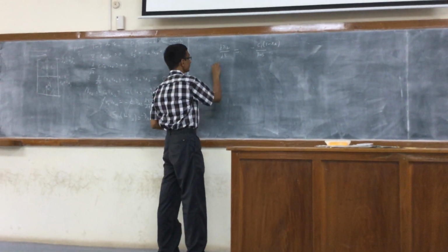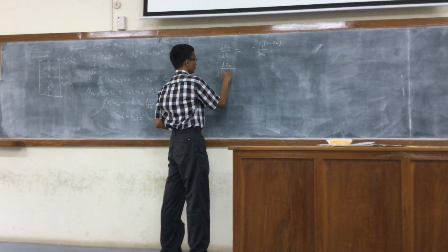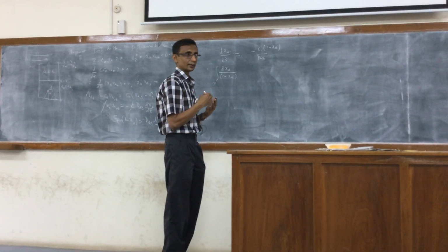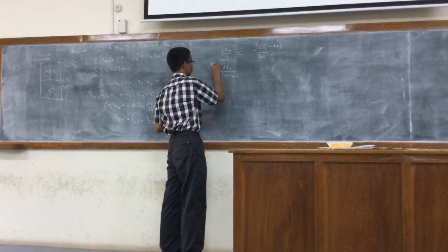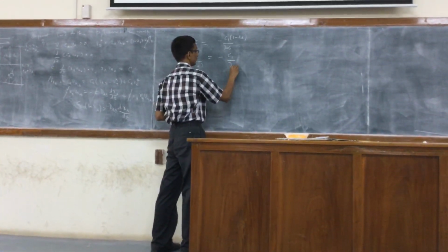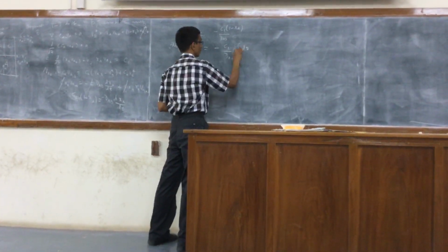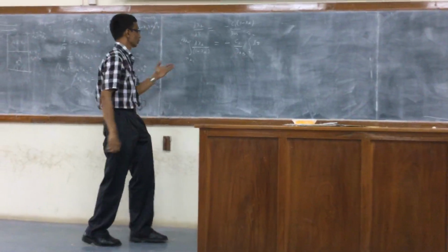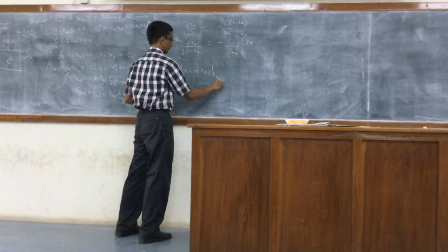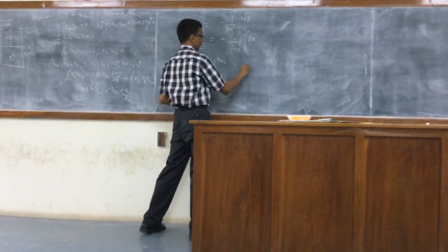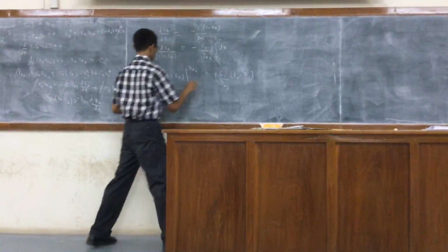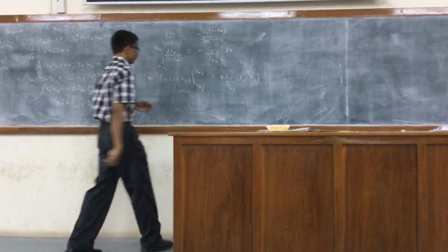So we now integrate this, it will be dXA by 1 minus XA. Suppose I integrate from, I can find C1 first by simply integrating this from XA1 to XA2, and then I have minus C1 by DAB dZ, Z1 to Z2. So this is minus logarithm of 1 minus XA between the limits, and this is minus C1 by DAB times Z2 minus Z1. We get rid of the minus signs on both sides.